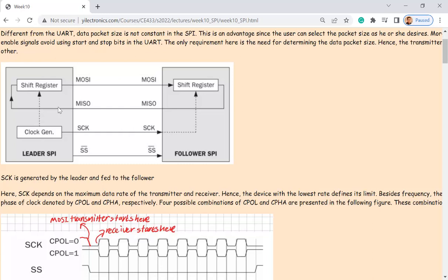But what you can do is, because the Basys 3 board doesn't have that module, you have to program it, which is going to be a receiver. The light sensor module is going to send data to the Basys 3 board, which performs as a receiver, and also it's a master. So you need a receiver module for the master.